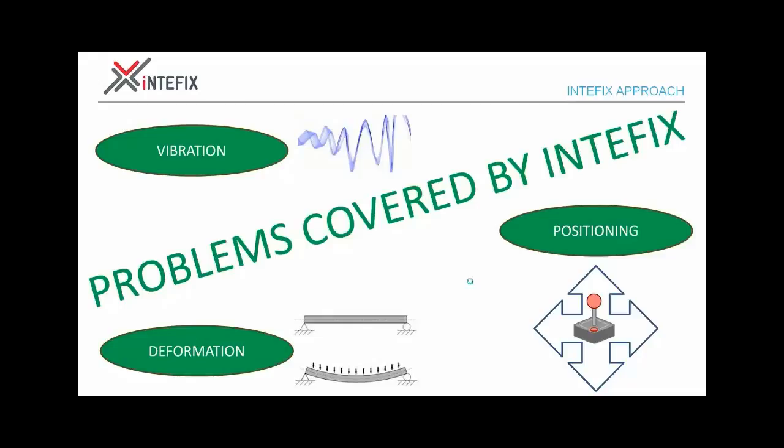So, in this case, vibrations can come from the workpiece itself, or maybe from the workpiece-process interaction. The deformations mainly come from the clamping forces or the residual stresses and problems that arise when the material removal is advanced and these residual stresses change the internal state of the workpiece, and then deformations arise.